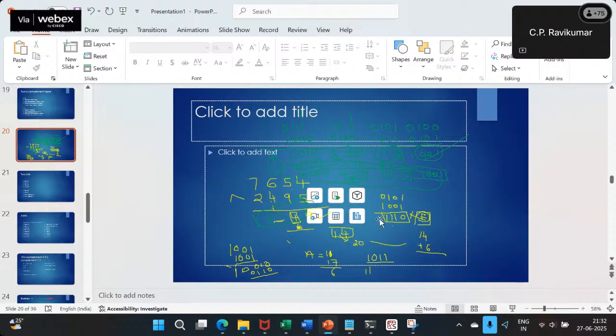Maybe we want to distinguish between the two. If the carry becomes 1, for me it's an event. If the sum becomes more than 9, then it's an event for me. So I can declare these as events, and maybe in the test bench I can check if this event has occurred, then increment some counter. So when I do some testing, I may want to get some confidence on whether I have reached certain corner cases.